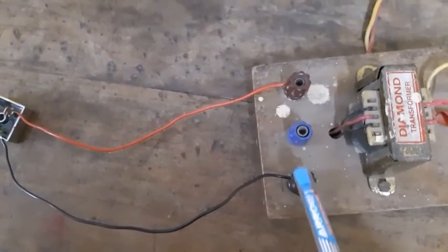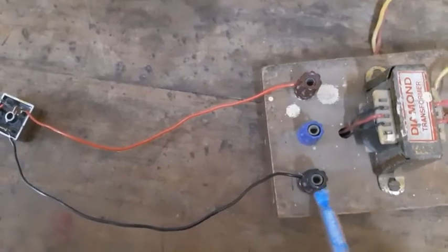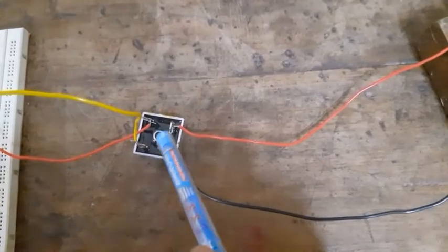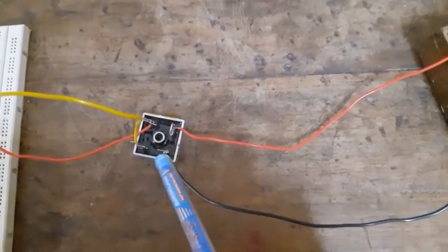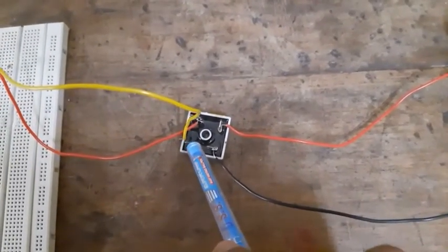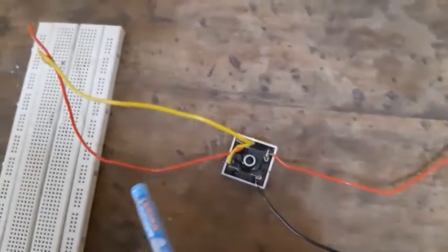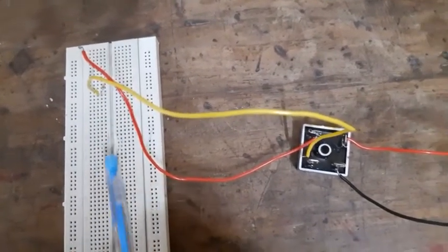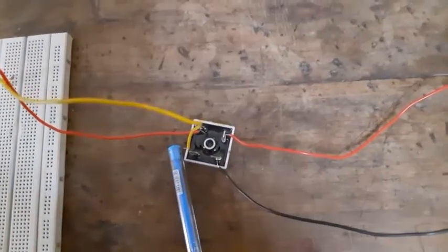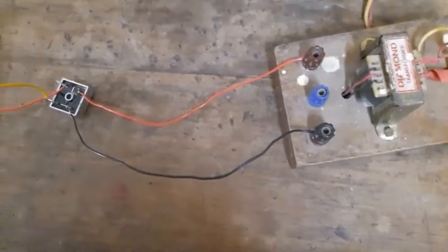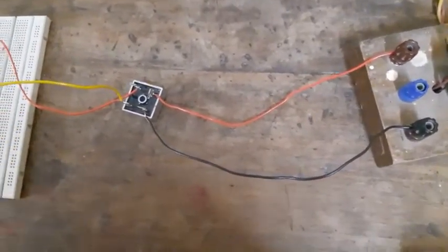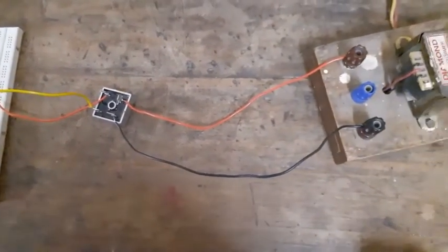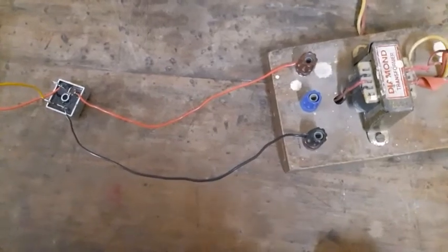Students, the connections are made as shown there. So the secondary of the transformer is connected to the 2 AC inputs, A plus and A minus, and then a resistor is connected across the DC output. Here the resistor is there, and it is connected across the DC output. These are the connections. After connecting the circuit, we will switch on the power supply, and then we observe the waveforms on the CRO.